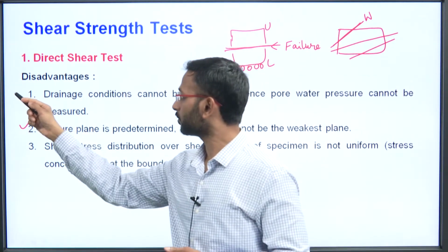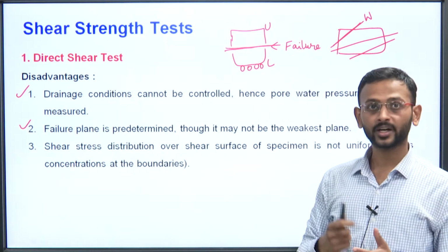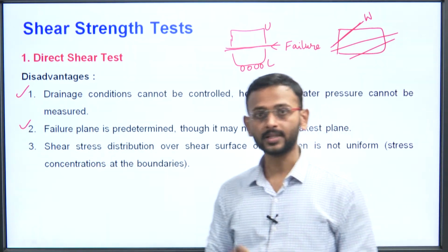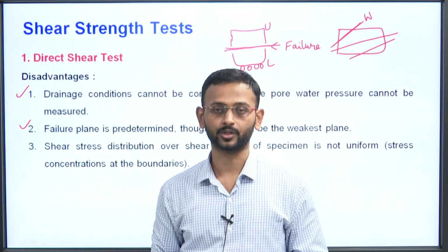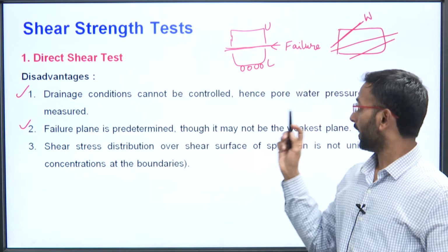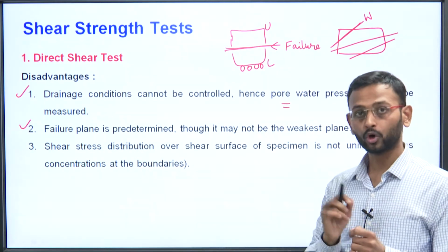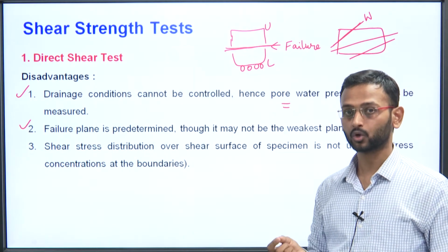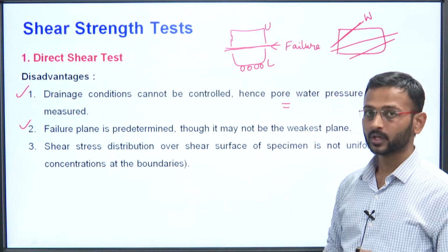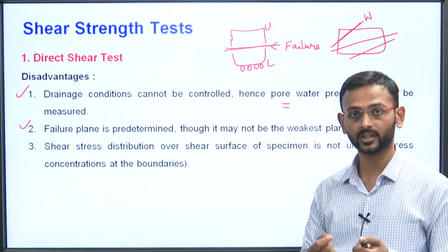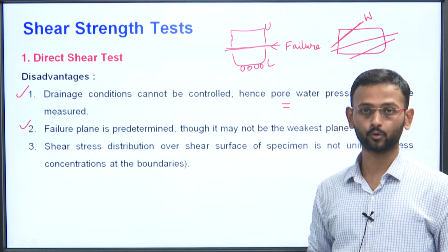And let us take out another point, that drainage conditions cannot be controlled, hence the pore water pressure cannot be measured there. And in actual field condition, the pore water pressure will be playing a very major role, because this pore water pressure will be affecting the shear strength or the bearing capacity of the foundation.